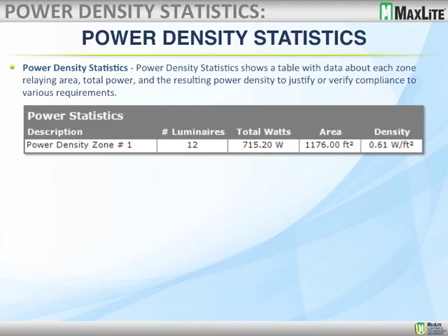So my understanding of this is that there are experts who are looking at what the absolute minimum watts per square foot can be. And as you mentioned earlier, we've come from 4-lamp T12s, where it was extraordinarily high, overlit applications. We really weren't looking at the cost of energy back in those days. So now that we're focused on it, the government is putting tax incentives in place to get us down to, in some cases, 0.75, and in the case of California, even as low as 0.5 watts per square foot. To calculate this type of information without a layout, is it even possible?